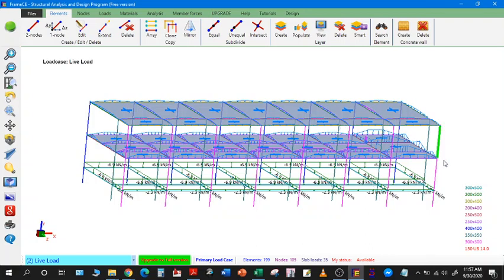But again, this is still up to you as a designer if you want to use that assumption or not. So if you want to be conservative, you can load the slabs with partition loads. Okay, but as far as this activity is concerned, our loads are already complete.